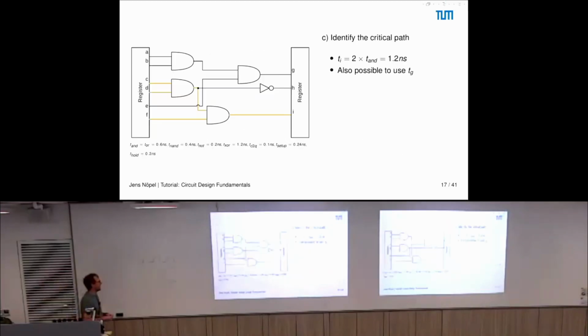All right, so maybe one short remark regarding the hold time requirement, because we haven't used it for the calculation of the frequency, and you don't need it for that. But you still have the issue that at this register here, it is important that after the clock edge arrived, the signal is still stable, because otherwise the new data may already get latched through if it changes at this point in time.